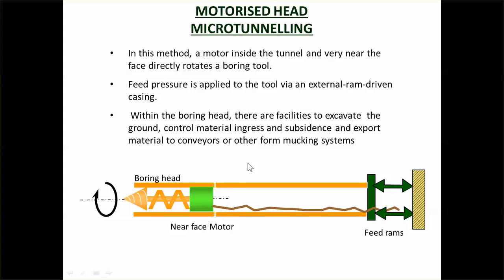The other way of doing pipe jacking, or a similar way, is microtunneling. The difference is that you're no longer just pushing it through, you're actually pushing, and you have a motorized head. So you have a little microtunneling machine, just like the tunnel boring machines that are being used for the Waterview tunnel, except these are little versions, maybe 600 millimeters in diameter, and they just keep on going through. The risk of that is if you get stuck, if there's a tunnel collapse or something like that, you can lose your machine.